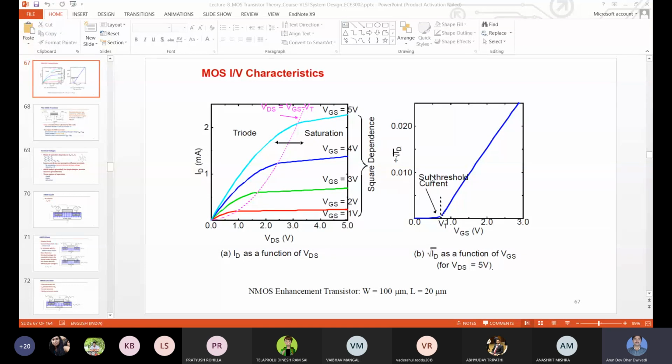So in the sub threshold region, it is assumed that for short channel devices, the channel is still present, even when VGS is less than VT but positive. So the channel is weakly inverted instead of strongly inverted, but weak inversion can be achieved at a smaller VGS. So at smaller gate to source voltages, still some leakage current we are considering. Some current is there, but it is very small in comparison to these currents. This small current flows below the threshold voltage.